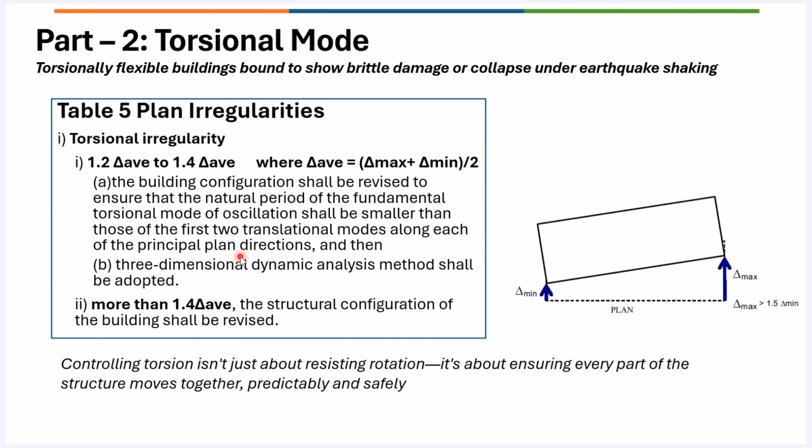And in case of a very high seismic region, even for short buildings, for example, a hospital building in a Himalayan region, then you cannot increase the strength. So in a highly seismic zone, with a factor of 1.5 or 2 for the demand force as importance factor, you will not be able to design such a building for these kinds of torsional issues. So what we'll be doing, you'll be considering building with base isolation, right?